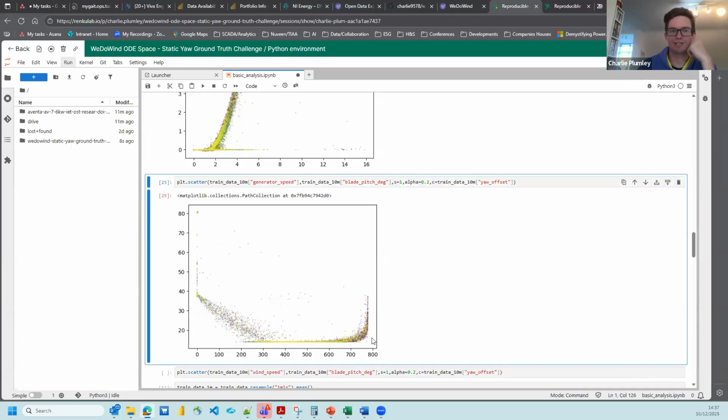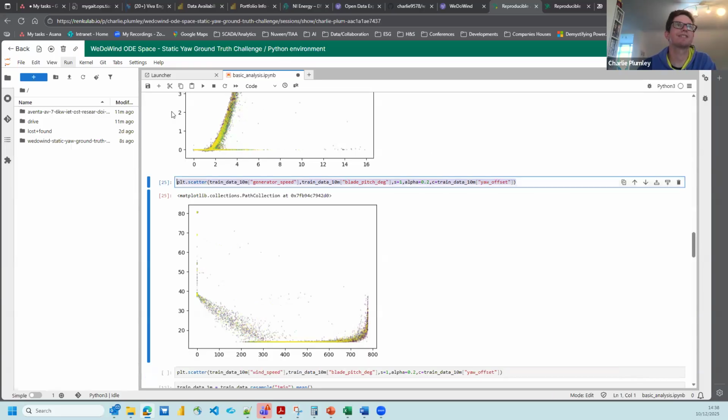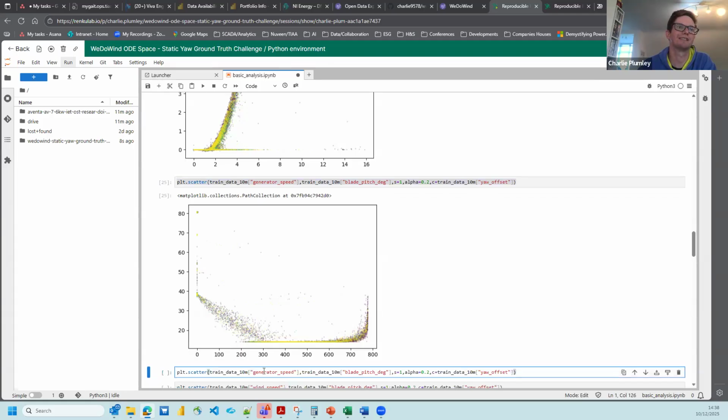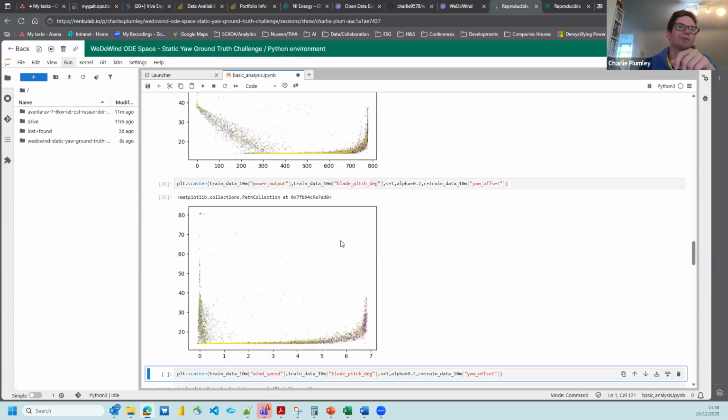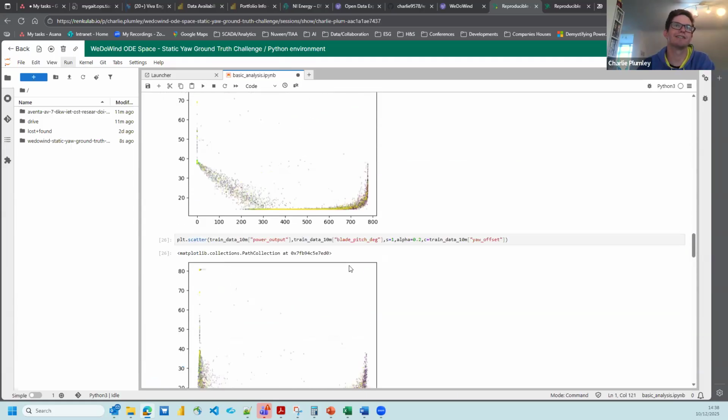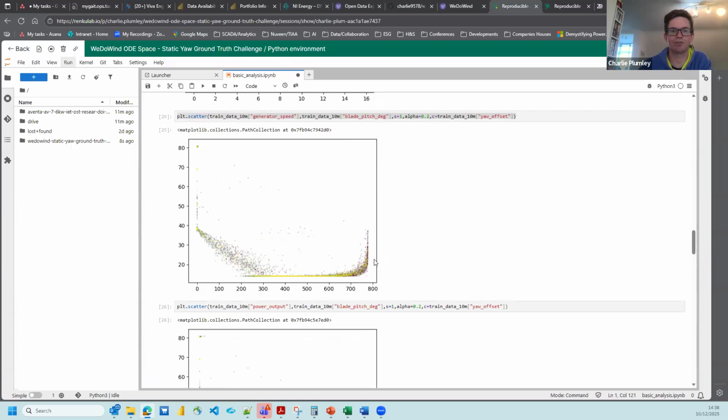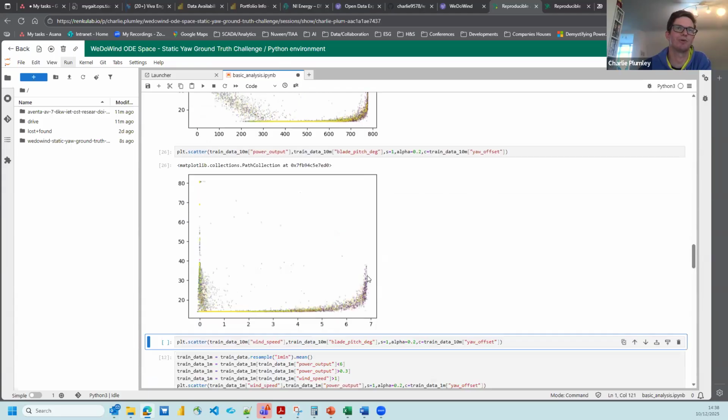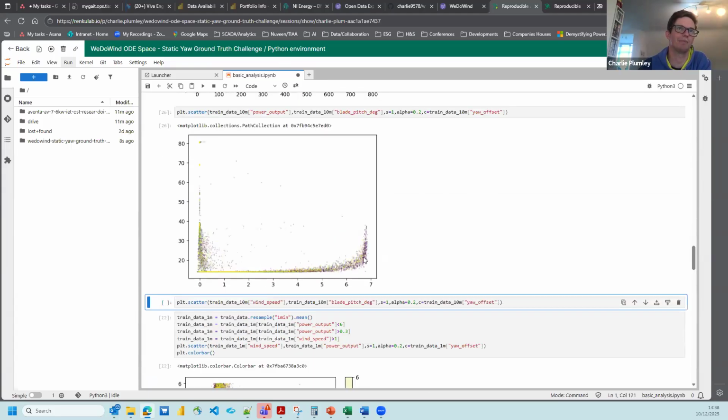The way you typically control a turbine is one of two, but they'll look the same because they kind of multiply. So typically you control the turbine so that it doesn't go above a certain speed by pitching, or above a certain power by pitching. So that's where you get the vertical lines for where we're pitching the turbine.